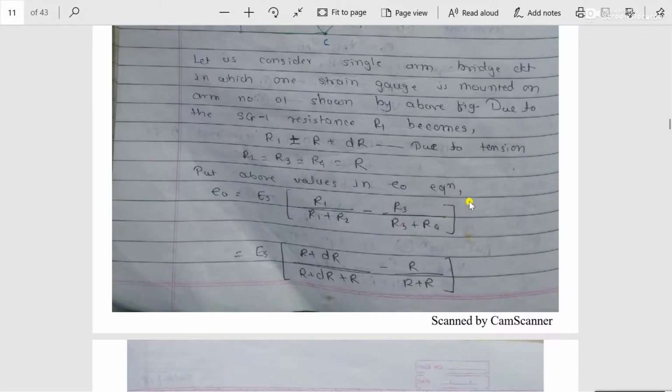This formula we have derived from the Wheatstone bridge circuit, but in the single arm sensitive bridge circuit we have two values, R1 is equal to R plus delta R. So put the value of R1, R plus delta R. Again at the denominator R1 is present, therefore R plus delta R. Instead of R2, which is equal to capital R, I have written capital R as it is, and the minus sign as it is. Then R3 is equal to R4 is equal to R, so R3 is replaced by R. Similarly, at the denominator, R3 and R4 are also replaced by R.